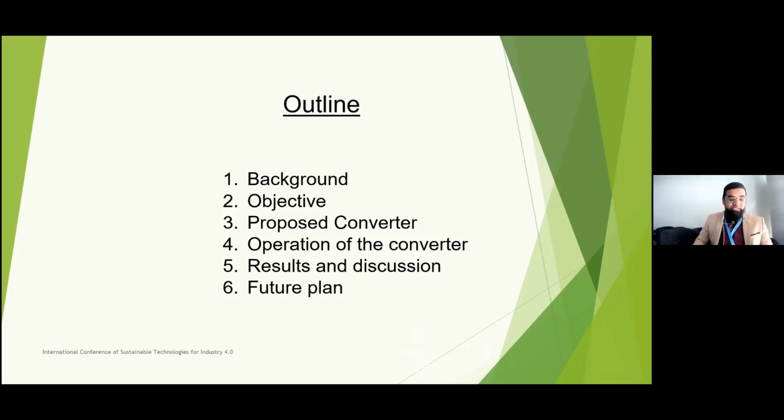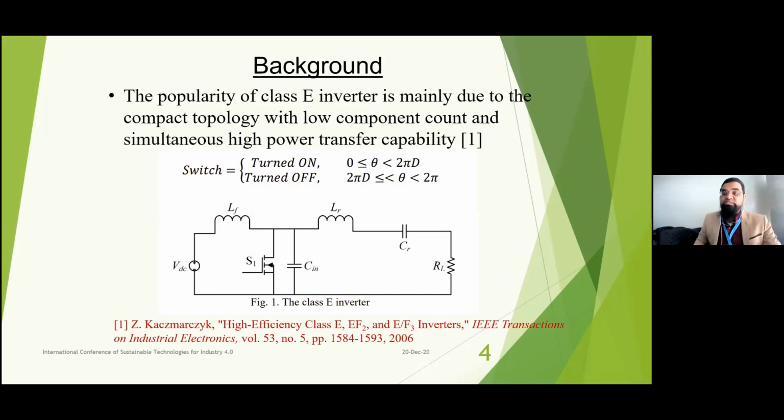So basically, this is a Class E based configuration, and Class E is very popular, especially in the low and mid power region operations. The popularity of Class E is mainly due to 3 or 4 reasons. First off, the compact sizing. As you can see, the number of components is very low. So that gives you a very high efficiency and very low loss in terms of switching and conduction losses. And they have a very clean operation. That means their EMI footprint is also very low.